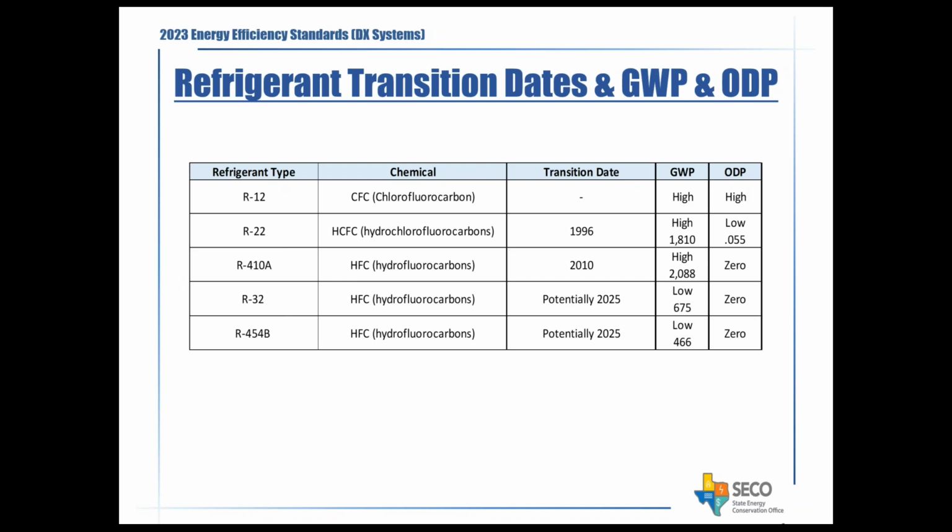That's why it is still recommended to vacuum and take the oil out of the system. There's also a recommendation for changing the indoor and the outdoor units. So I suspect that will have an impact, and probably there are some differences.